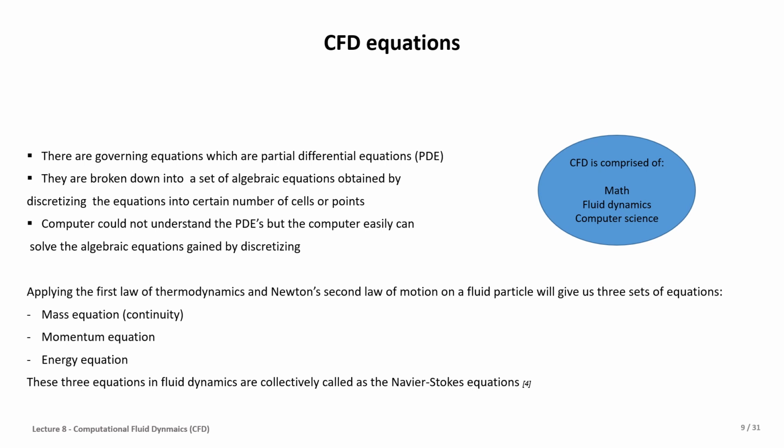When discretizing the domain of the problem into a small grid, which could be elements or grid points, these PDEs will be converted to algebraic equations, and then the computer power could be used to solve such equations. In fluid dynamics, the governing equations are the mass equation (continuity), the momentum equation, and the energy equation, and these three equations lead to the main equation of fluid dynamics, called the Navier-Stokes equation.